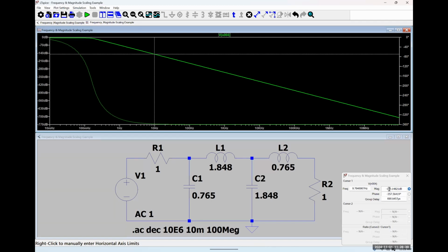This is used in a lot of power supply filtering where we intentionally don't want to add noise to our signal and things like that. Just for what it's worth, this is what's known as the Cauer topology. The Sallen-Key filter topology that I gave you guys for your second design project is a different way to do Butterworth filters as active filters.